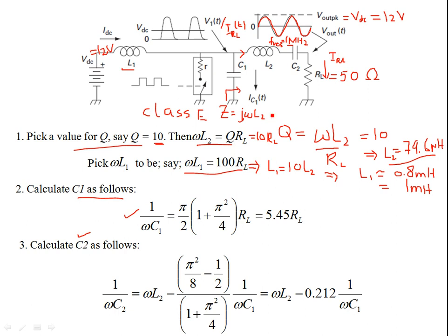What do we have else? So we have minus j over omega C2, and the last term is plus RL. So that's what it is. You see, the node voltage is V1, that is the capacitor C1. That's the same node voltage at the JFET switch, divided by the load current, which gives you the impedance.